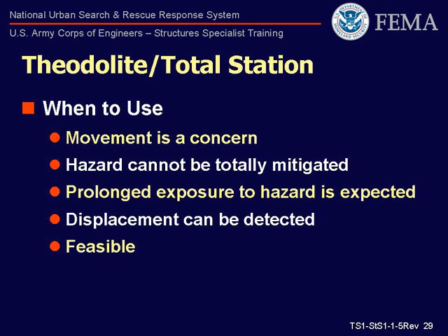appropriate. For example, monitoring a potential catastrophic collapse of a concrete floor may not provide adequate response time for rescue personnel to evacuate safely. The first choice in dealing with the hazard on a rescue site is to mitigate the danger posed. This may be as simple as marking the affected areas off with caution tape and avoiding the hazard. Typically, if there is going to be a period of operation within a potentially affected zone greater than 12 hours, a mitigation or monitoring plan should be established. Bottom line, though, is the total station should be used where feasible.